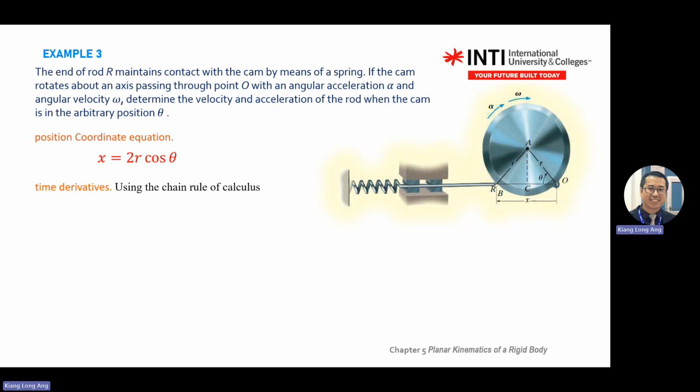Once you have the position X, or the displacement equation, X is linked to radius and cos theta. So if you see something that links rotation to linear, this is how you do it. You try to build a triangle, then find the change of angle between these two. Once you have X equal to something with R and theta, you need to find velocity. Velocity is dx/dt or ds/dt. Acceleration equals d squared x divided by dt squared. So you need to do differentiation here.